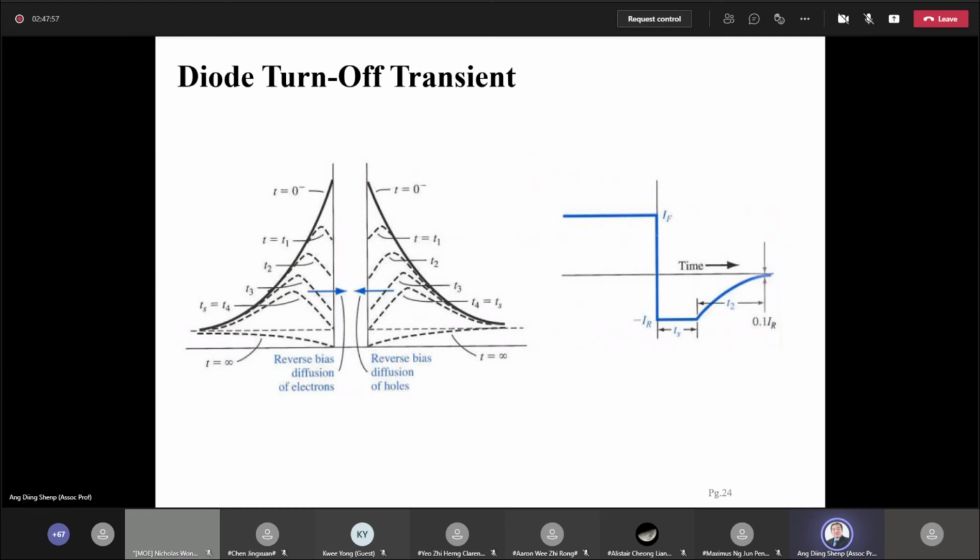So with that, that concludes this part of the discussion on junction capacitances. To summarize, there are two types of capacitances: junction and storage capacitance. Storage capacitance will dominate under forward bias, whereas junction capacitance dominates under reverse bias. It is the storage capacitance that controls the transient response of the PN junction, and therefore this becomes an important consideration if you try to use a PN junction diode in a circuit that is meant to operate at high frequency. So with that, we finish today's class.